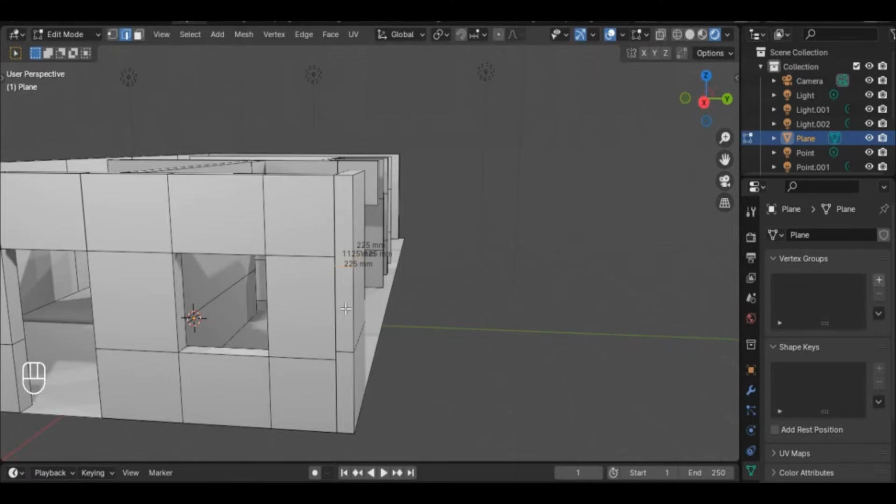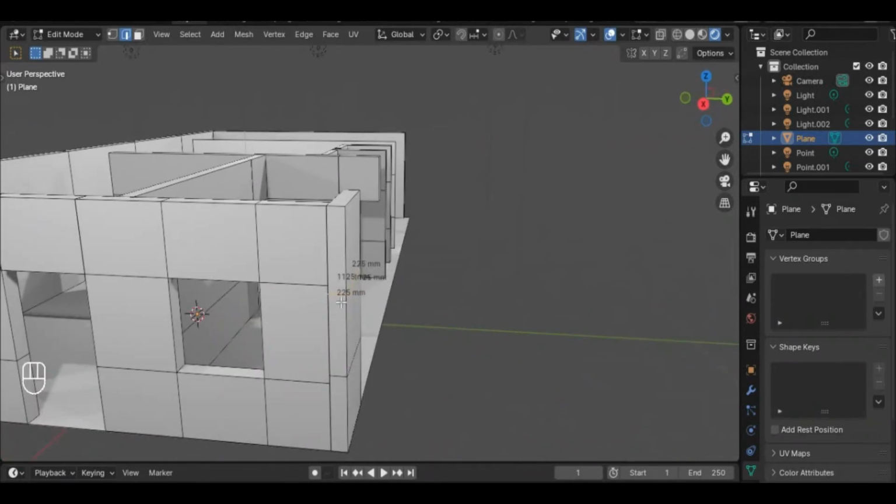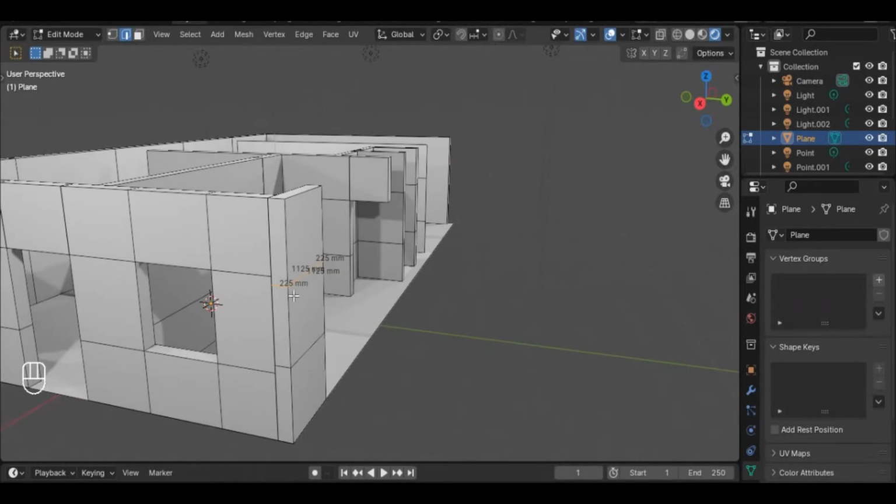But when it's on the same line with this, or maybe it's very, very close, dangerously close, and you want to move it to a different place, like when we are drawing the toilet window, it's going to be on the same line. We have to move it to a different line. Then you can now use your Shift Alt left mouse button to highlight from the part that is freer that you can choose from. So let's move this up 100 to level up, and we'll also move this.